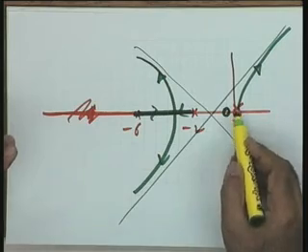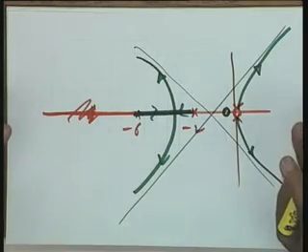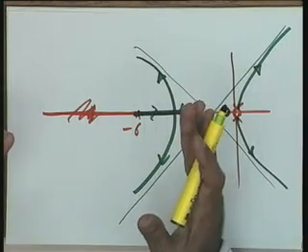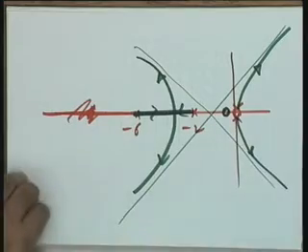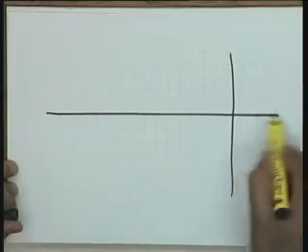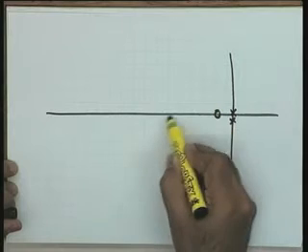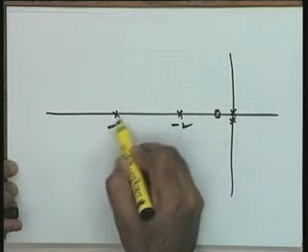But this particular pole has drastically destabilized the system, and now I want to stabilize it again. I want to pull it back, and I can pull it back by placing a 0 close by. Help me please. If I place a 0 close by, what is going to be the root locus sketch? A 0 close by, a -2 here and a -6 here.